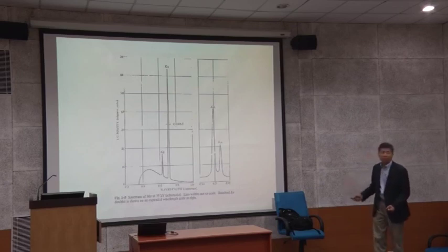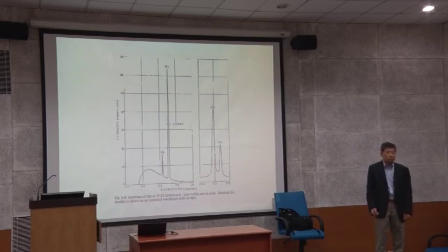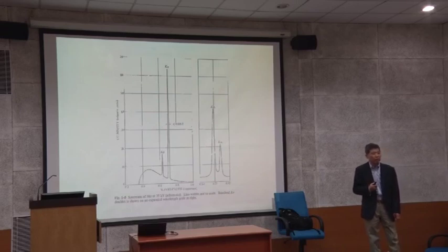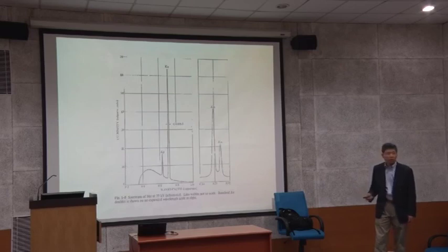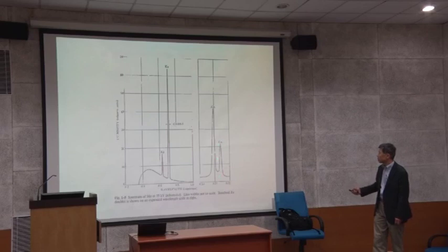The peak is not perfectly symmetric, but you commonly use that average. But if you need very high resolution X-ray to determine crystalline quality and those things, then you use a different type of monochromator. You cannot use a nickel filter; you use a multilayer monochromator, and you separate this and remove this one, and you only use this.